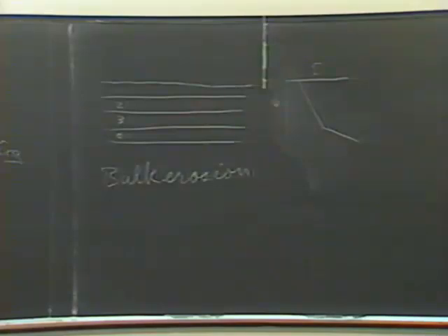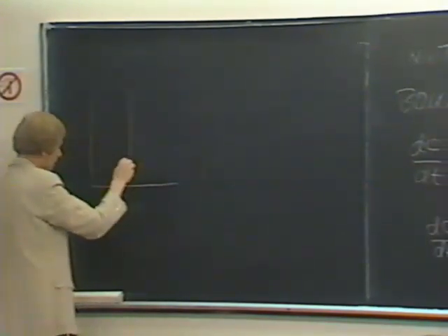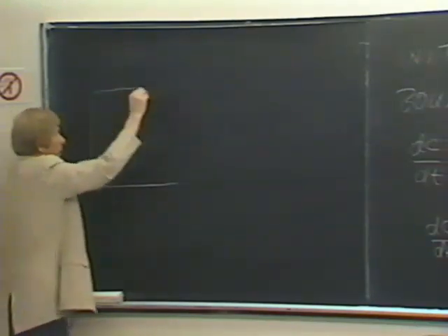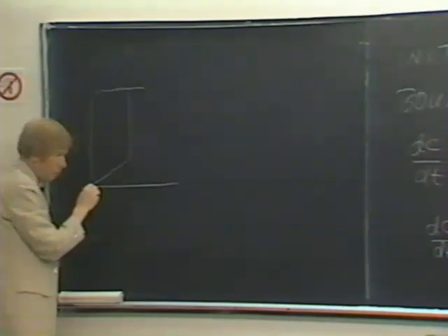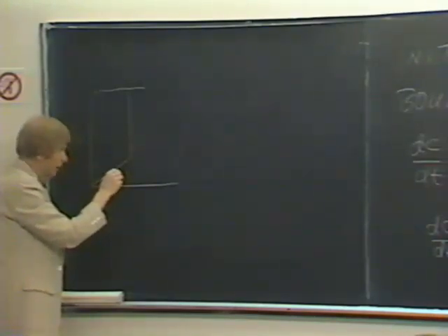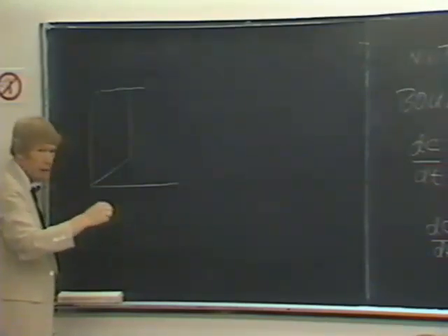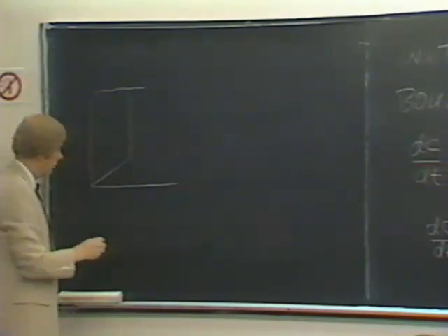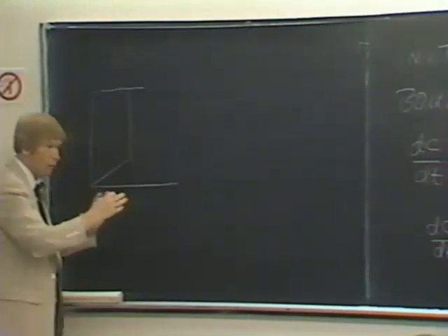we assumed that a velocity profile would look something like this. That is a 2-part profile with a plug flow. This is the top. Plug flow in part of it, and then a velocity gradient in the lower part. And for lack of better information, we assumed this to be a linear profile. We haven't yet found any way to measure the velocities in mud reliably. So not having anything but the external velocities at the top, it appeared that it was plug flow.